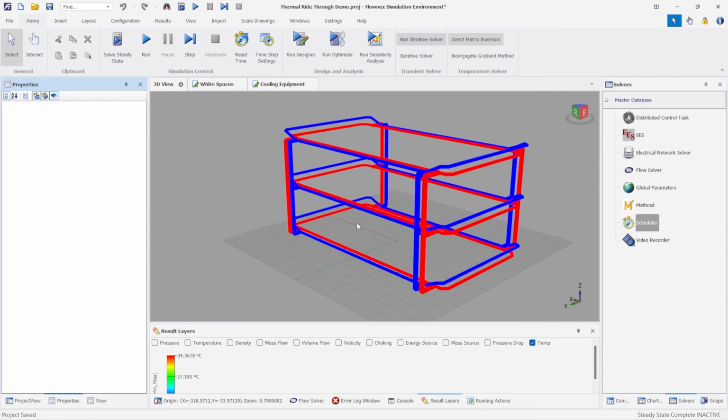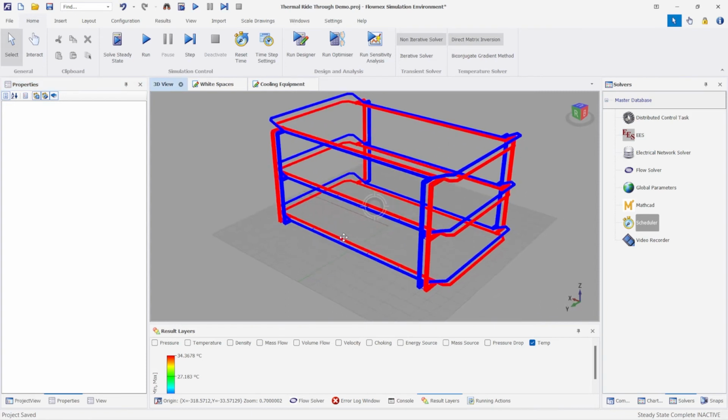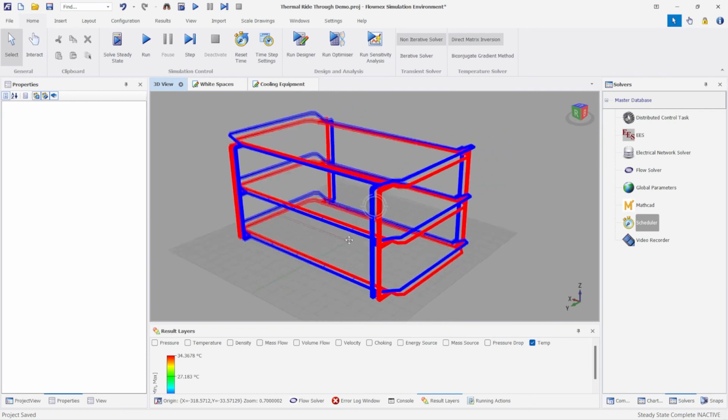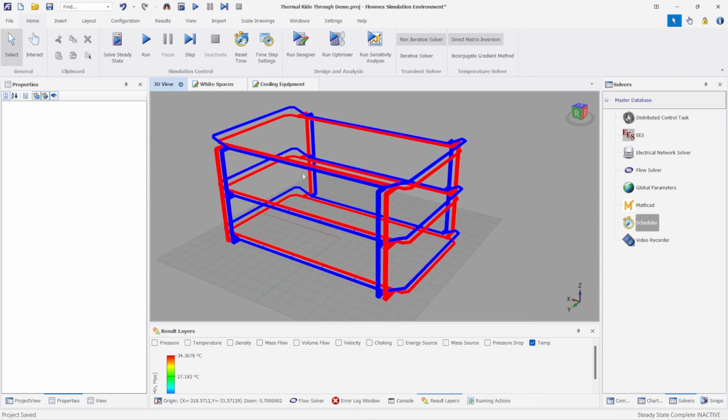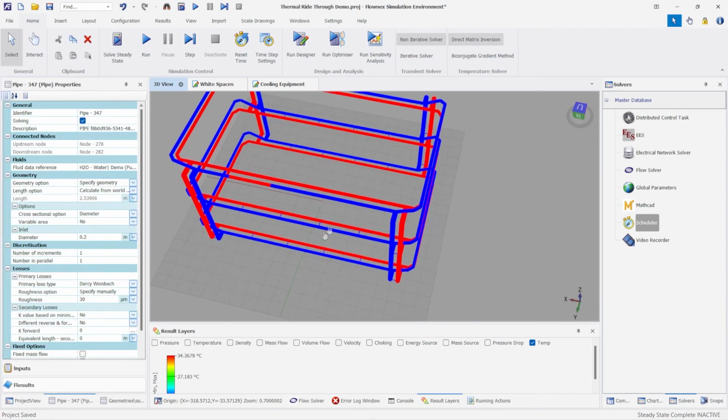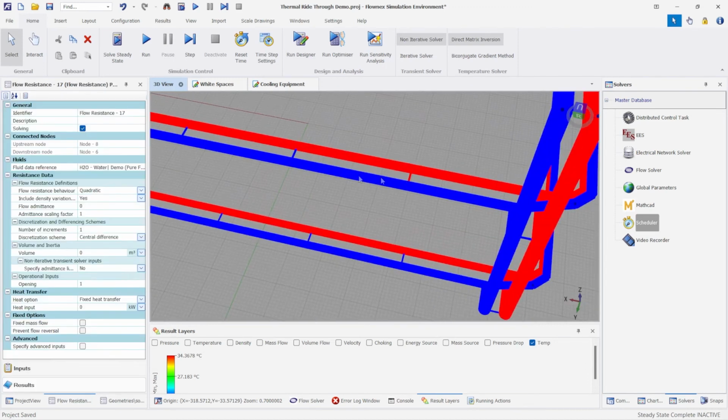So first, we're looking at a representation of the piping in the system. As I mentioned earlier, this is a PCF file that was exported from Revit and imported into Flownex. You can see each of the pipe components being modeled over here. And then in between the pipe components, I've just inserted placeholders to represent the points where we would connect CRAHs.